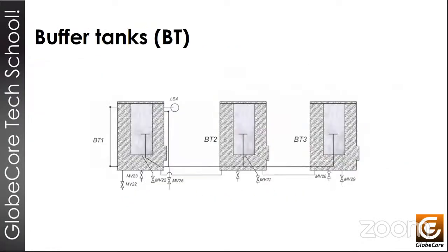Next slide, please. These are the buffer tanks in the machine. These containers are designed to contain oil, both for processes in which the oil level drops as a result of the regeneration process, and for the reactivation of the absorbent material. An additional characteristic of these tanks is that there are actually 2 of them, 2 tanks in one. Inside the main tank, you can see there is one more smaller tank that collects pollutants and water and condensate during the Fuller's earth reactivation process.